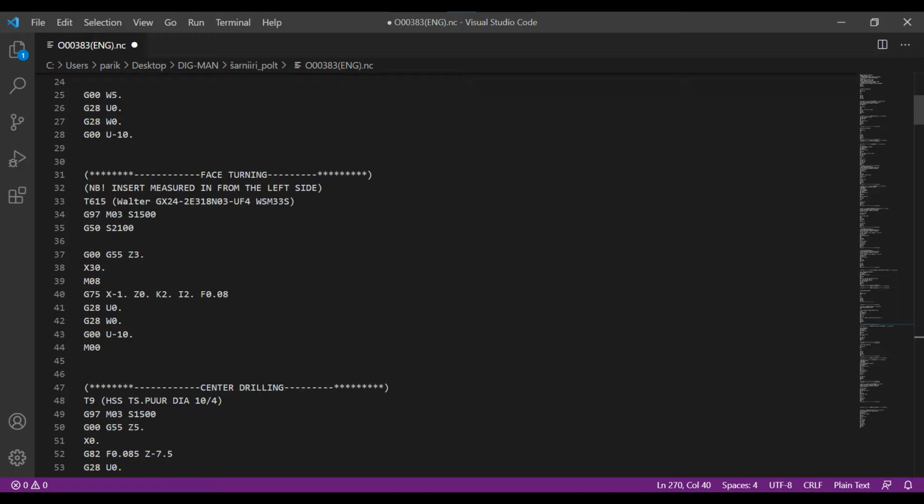Starting the spindle is always done before any movements. That way, if the tool crashes into the workpiece, it starts cutting instead of being just pressed against the workpiece, and there is some chance that it can survive. Crashing into a stationary workpiece usually ends up with a broken insert due to the brittle nature of carbide.